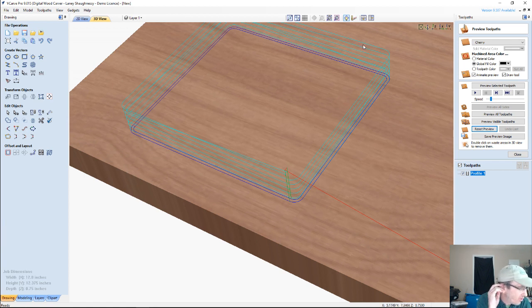I watched the toolpath in the software, and it was taking a slow ramp of about 20 thousandths of an inch, 0.02 of an inch, as it was going down, and it was taking more and more.